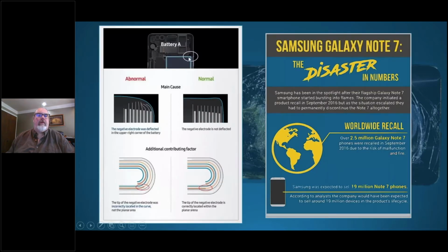In the corner up here, where the battery went together, the normal design should have been closer to a 90-degree angle, and the different layers inside, they call it a jelly roll, and I'll talk about that in a second, should be laying flat. One of the problems they had was the case was a little small, there were some protrusions underneath, and it put a crimp in the corner, and that caused some of these layers to contact each other.